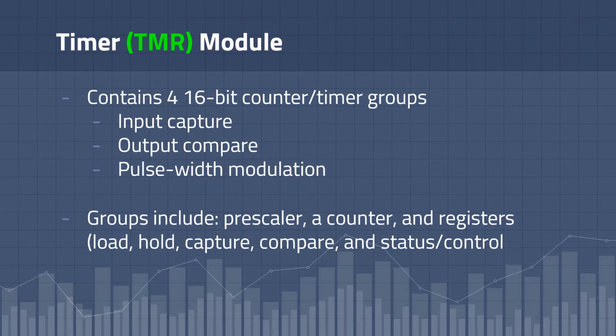Timer module. The timer module is used to count internal and external events and reconcile these values with predetermined values. External inputs are shareable, can be used for both timer and counter purposes. The module has 4 external timers, input-output pins, and each counter timer has a variety of function modes in which it can operate. There are 3 primary functions for the timer module.